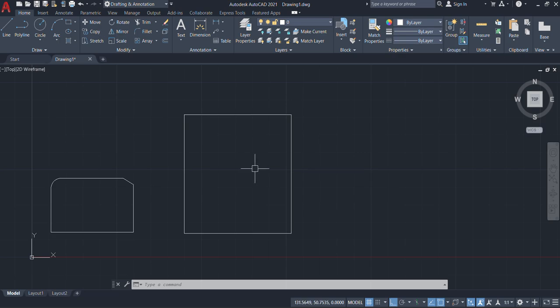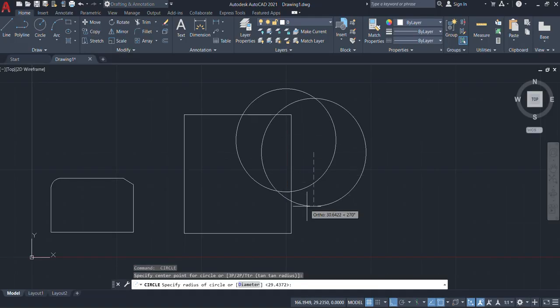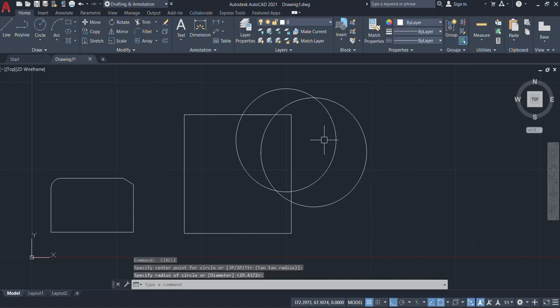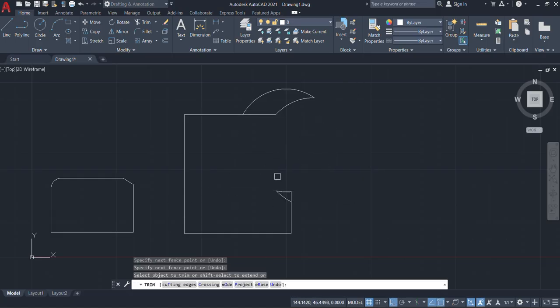Okay, same as well, here we have the trim. You already know about this trim, right? So I'm drawing like this. If you want to delete, if you want to erase any unwanted portion, in that time we have to use the trim. Here double enter, otherwise go with TR enter. In the latest versions, you can give TR enter. Okay, in old versions, we have to specify TR double enter. So like this, we can delete the unwanted portions of our object.